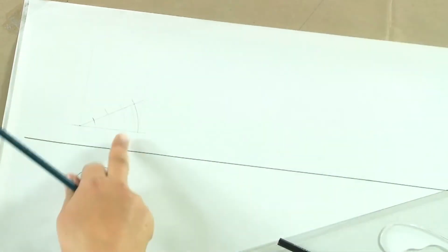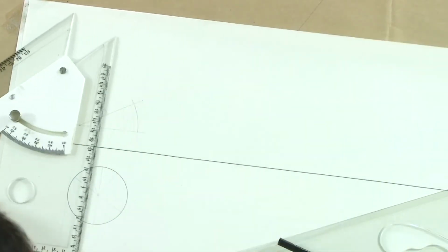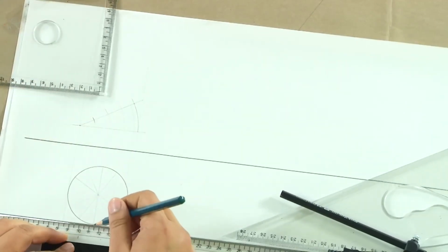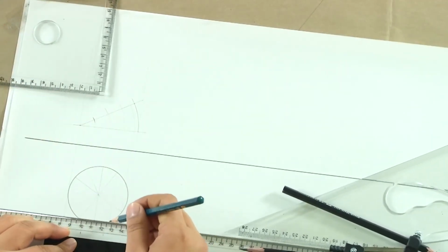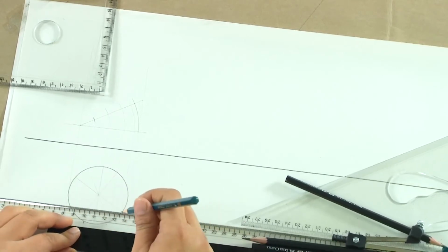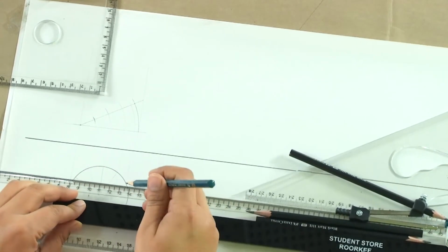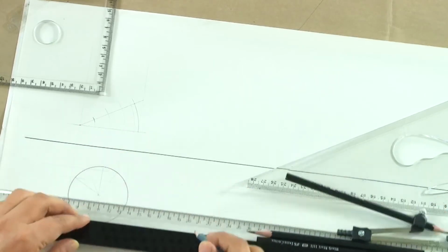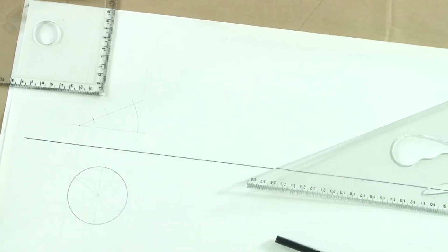So, this is the vertical projection, and what we have to do? We have to bring it back to match the horizontal projections. Since we are inclining it with HP, and if you remember how we inclined the lines, the doubly inclined lines or the singly inclined lines, we only take the locus of the point in one plane, it just remains the same.